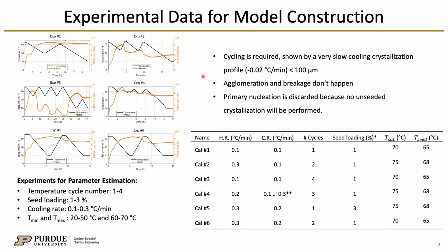Compound A crystallization is a cooling crystallization process. Thus, all the experiments were started with a cooling ramp to create and grow initial crystals. Six training experiments were done with different heating and cooling rates, number of temperature cycles, and seeding conditions. These heating ramps were implemented to achieve the required minimal crystal size, and thus information of necessary temperature cycling was gained from our previous studies.